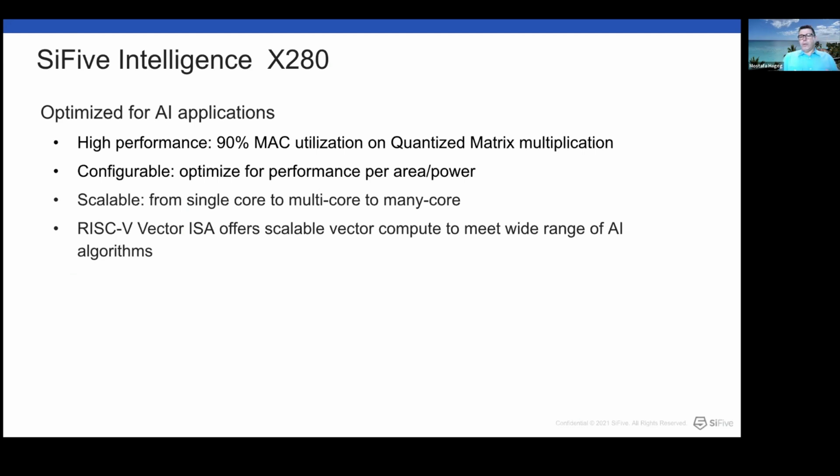One of the key metrics and the way that we look at a good design in the X280 is really to measure how much you can use these TOPS. Besides analyzing performance for many of these layers and end-to-end performance of inferencing workloads, we look at how much we are able to tune the microarchitecture, the compiler scheduler, and the hand-tuned intrinsics in order to achieve that high utilization.